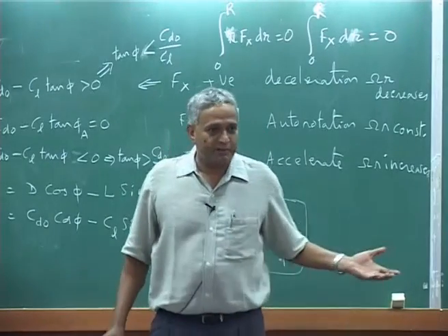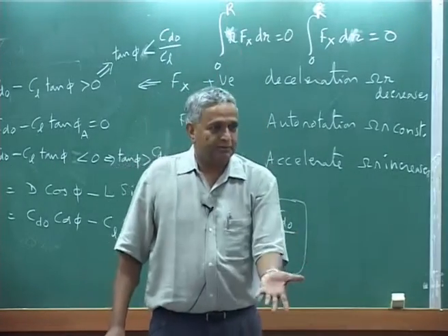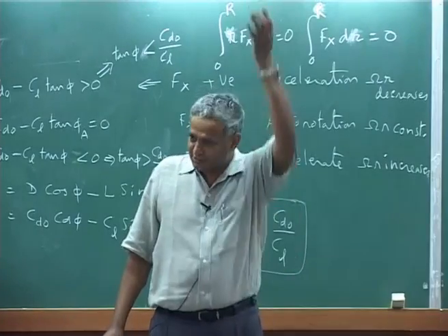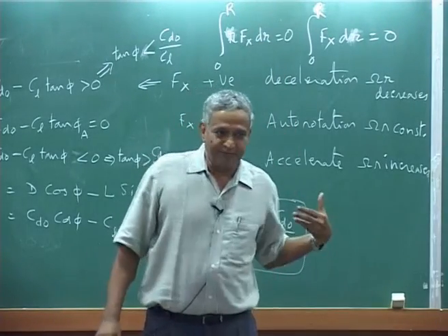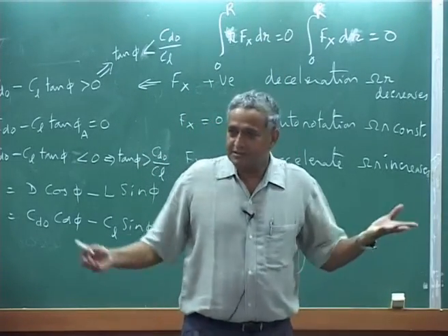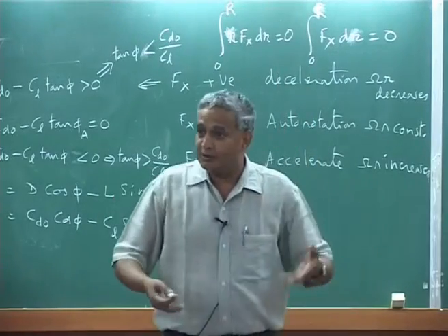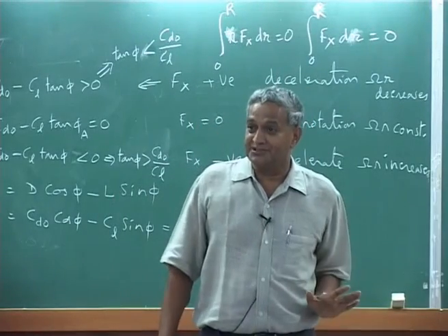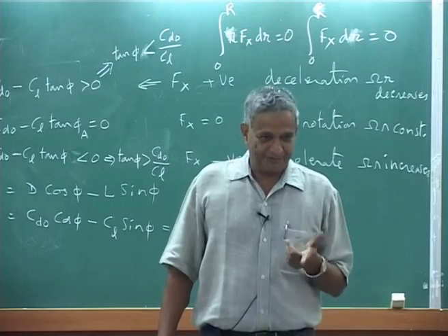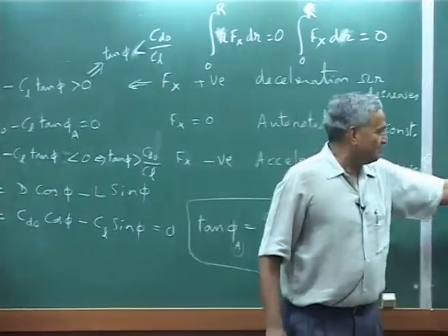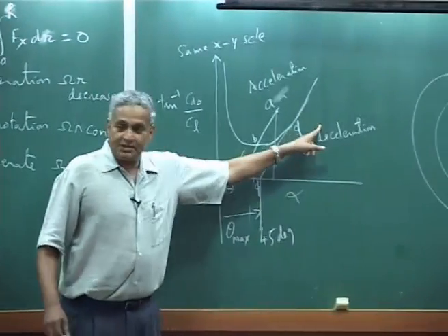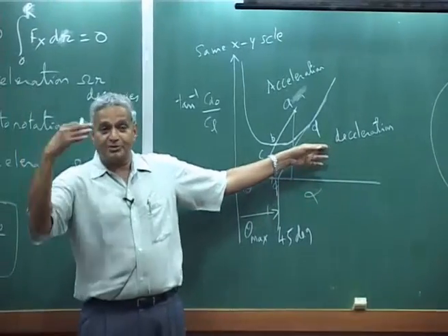Because in autorotation, what is going to happen? The helicopter is going to come down, the engine fails, because there is no power, it is going to come down. At that time, what you have to do? You have to decrease it, you follow, because if you are here, that is all, your rotor will stop and it will start rotating backwards.